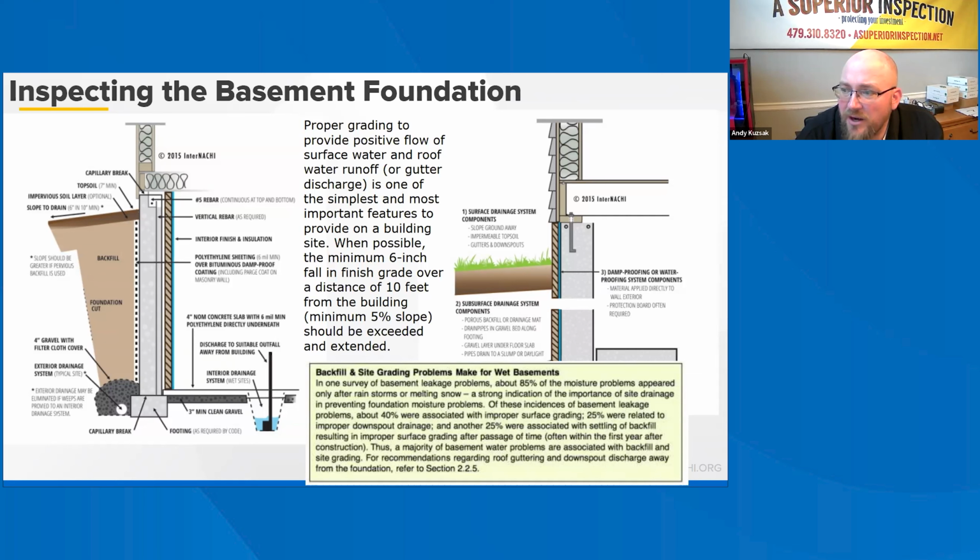On flat sites, this may require mounding of the foundation pad and coordinating appropriate foundation elevations to promote drainage. On sloped sites, excavation and grading in the uphill direction must provide sufficient drainage away from the building perimeter and against the direction of natural water flow on the site. For steep slopes, a retaining wall at the toe of the slope may be necessary. Controlling grading and backfilling operations in typical residential construction is challenging. Common practice on many sites involves placing backfill with minimal effort to fill the hole. Proper backfill practices and grading will ensure that the foundation remains dry more effectively than other recommendations.